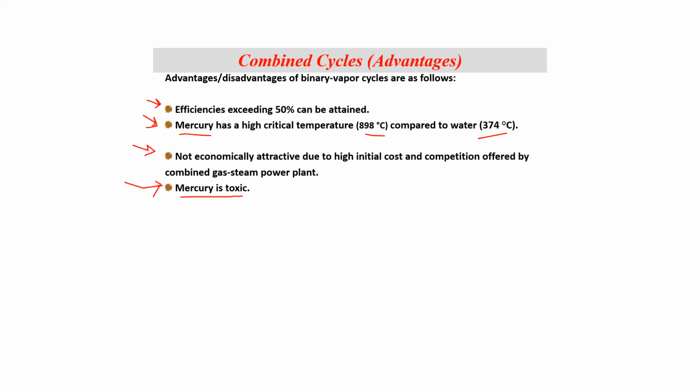Regarding that, I will recommend that you solve the later examples we saw by yourselves, and also the examples 9-5 to 9-7, and try and solve examples with, for example, two intercoolers and reheaters or three intercoolers and reheaters, and just see the effect of regeneration. Assume the regenerator effectiveness as 100% or 80%. Just see the effects of all of these.